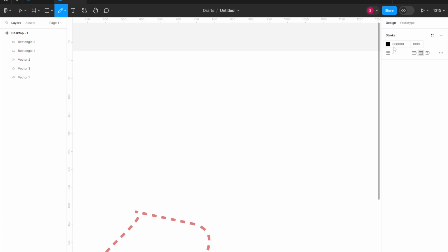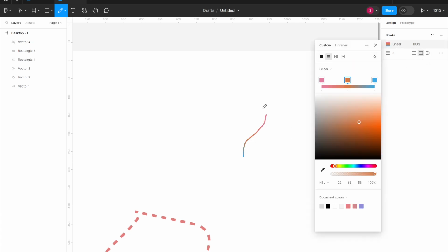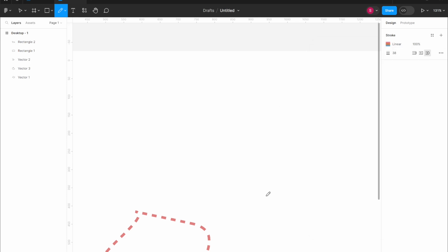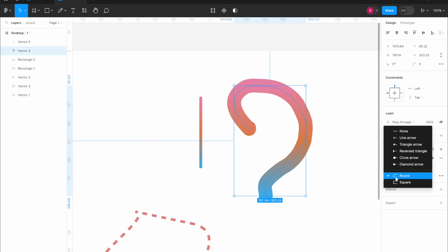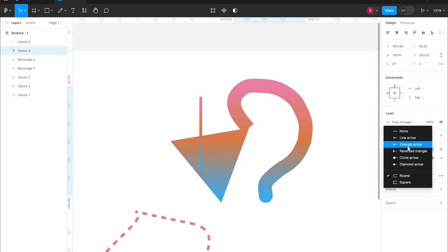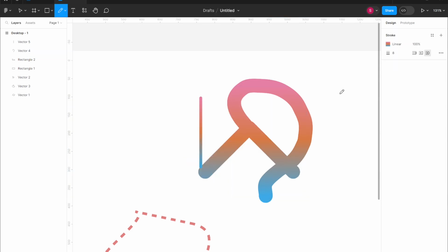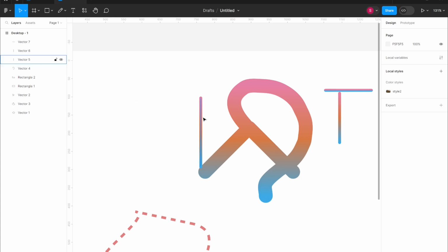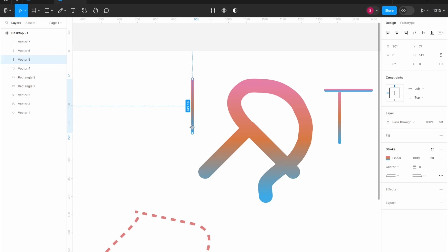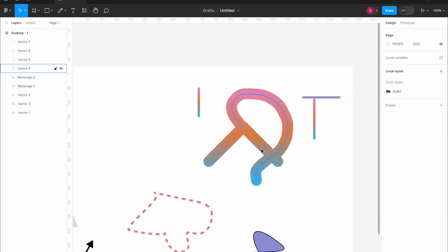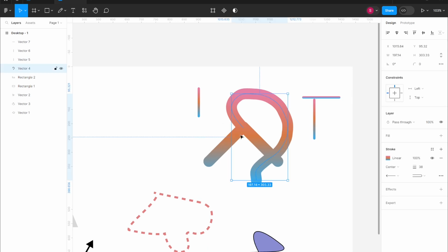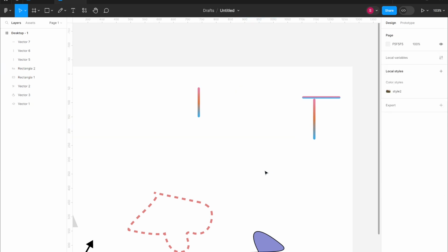We can choose, both before or after, a fill color, stroke weight, and endpoint style from the section, because again, we can put caps and decide the shape of the caps. As always, of course, just hold down Shift while drawing to have a straight line, and the pencil tool remains active until you select another tool or press ESC. The pencil tool corresponds to a vector path. It does not use pixels, and therefore the drawing will always remain sharp. To delete a pencil sketch, there is no erase tool, but just select the sketches you want to remove from the drawing area or the layers panel and press delete.